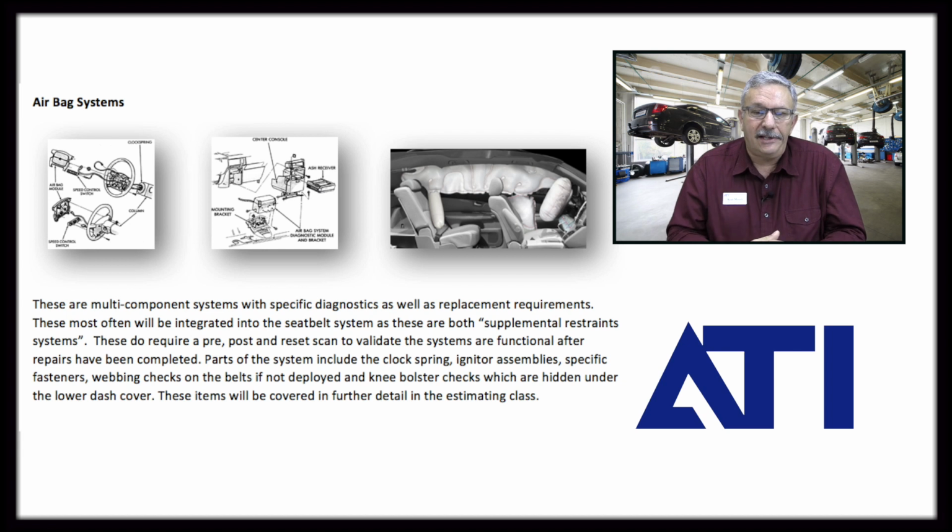If you have somebody that's of significant weight that hits the airbag system, there's also a collapse capsule in the steering column that manufacturers give very specific measurements for. It's wise to go in and just check the distance and make sure that the distance in that crush cap is where it's supposed to be, because if not, then the steering column itself has to be replaced. So these are pretty important things in that whole integrated airbag system.